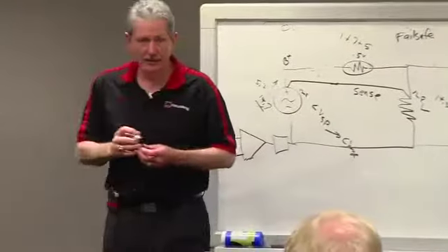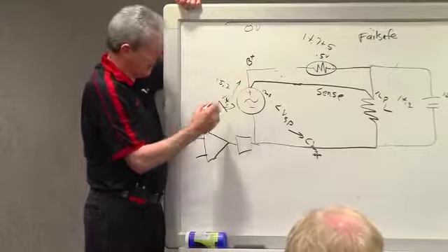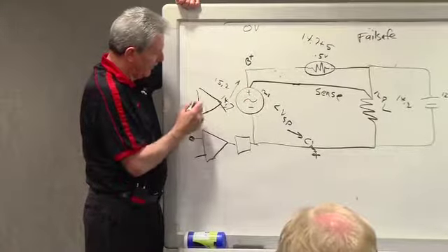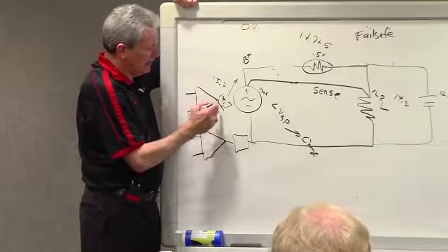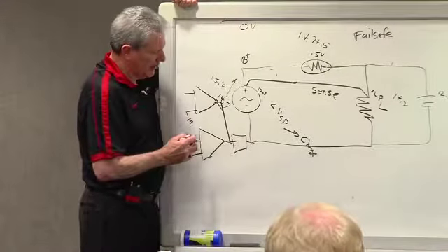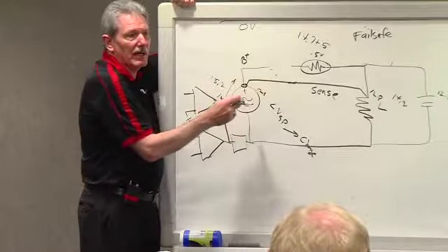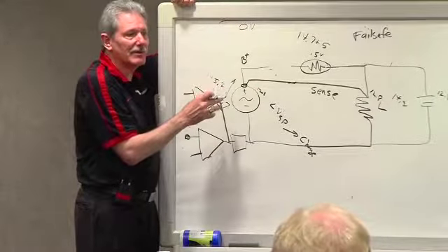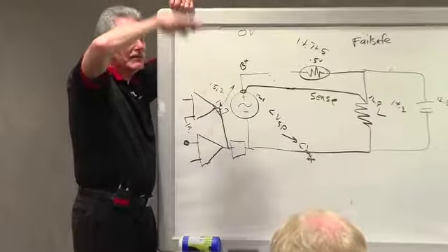Fail-safe does two things. It has another set point in here, another comparator, which is like 19 volts, that goes back over here to the switching circuitry, and it says if this voltage, whether I have sense or not, goes up to 19 volts, shut it off. So now it's switching at 19 volts.